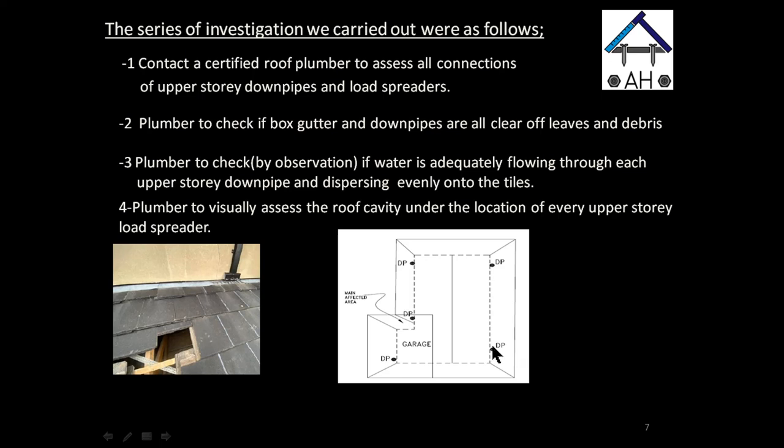garage. As seen in the plan below, you can see here that there are 5 downpipes in the upper story with wrongly installed spreader pipes. That dashed line here represents the upper story walls, which is entirely offset from the lower walls, as you can see here. So you could imagine that the lower roof is located not only around the garage area, but around